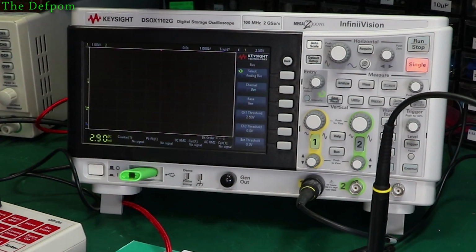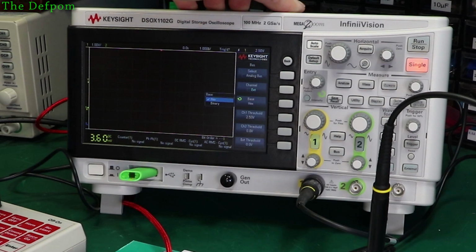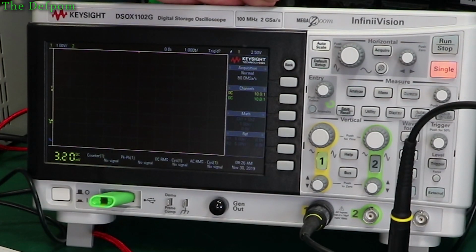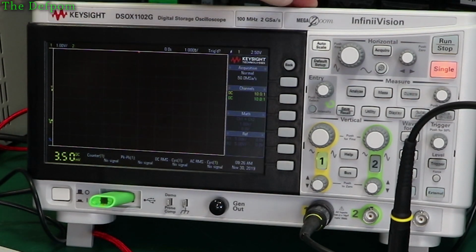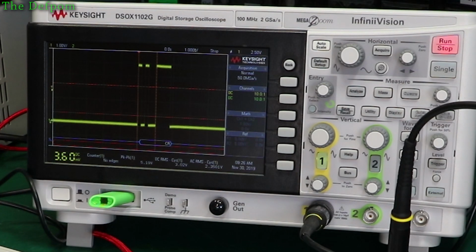So if I look at the bus settings, I'm using just the analog bus because it's using the channel 1 input. Your hex or binary base for that, whatever. Let's trigger it and actually show a signal, shall we? Now I've got a 1 volt per division setting, and we're also at 1 millisecond per division. I've got it set on single capture, so let's push a button, do a start, and there's the initial pulse.